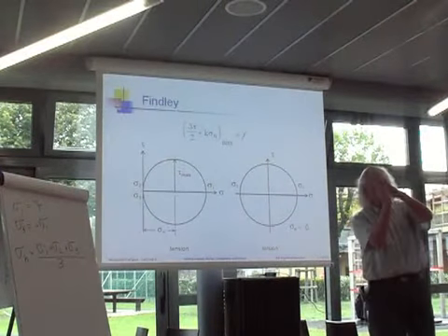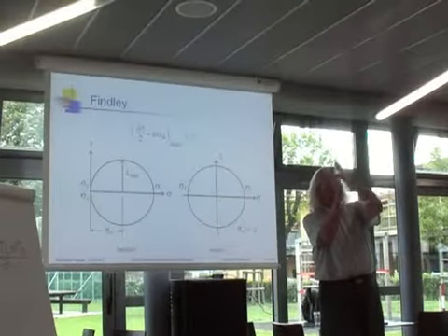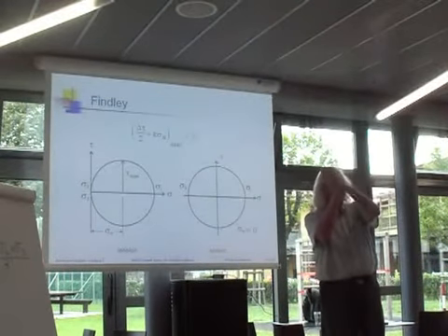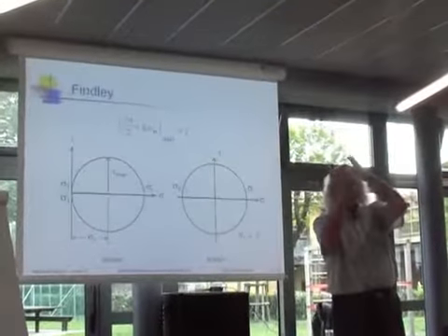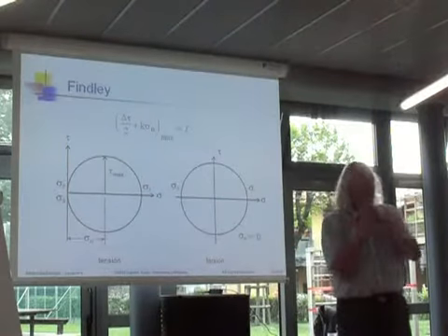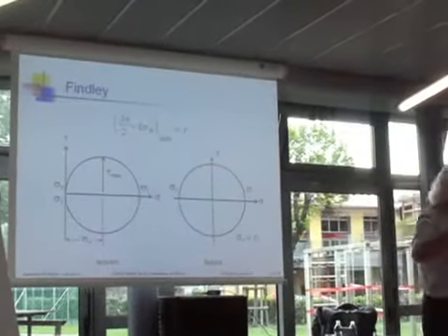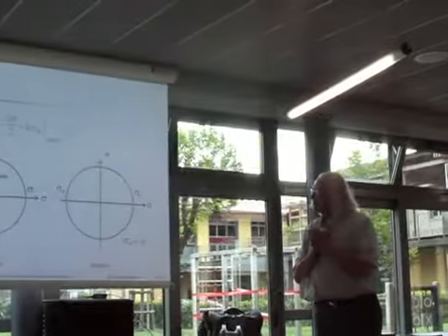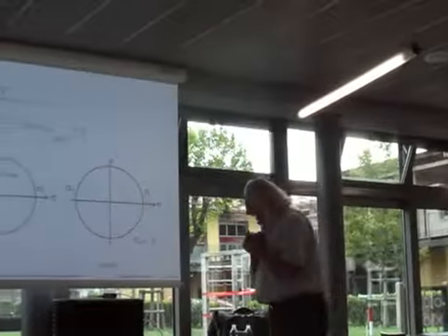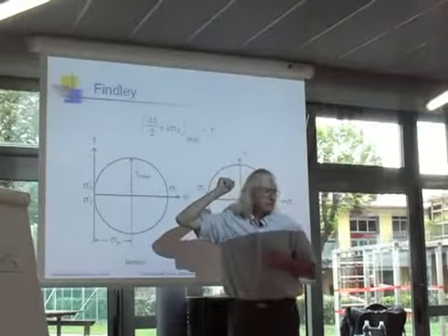Because in tension, I am shearing this with a mode 2 cycle, but I also have a mode 1 cycle at the same time. And this mode 1 cycle will eliminate the crack face friction and so on, as we have discussed. Right? And that was Finley's idea. Okay? And then he wanted to express this, and so he said, fine, the driving force for fatigue will be the maximum shear stress.